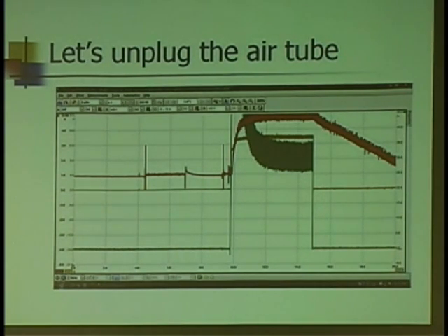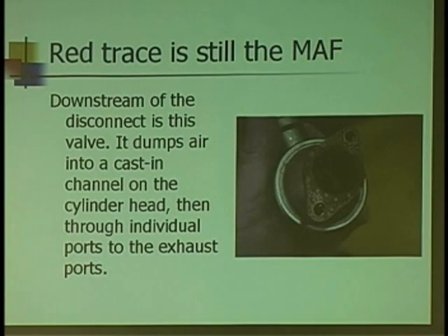And where I'm unplugged, there's only the check valve, the exhaust manifold, and the individual ports going into the head. This car's got 35,000 miles on it. Are they clogged? I wouldn't think so, with that low mileage. So I'm thinking, what about this? Let's look at the check valve.